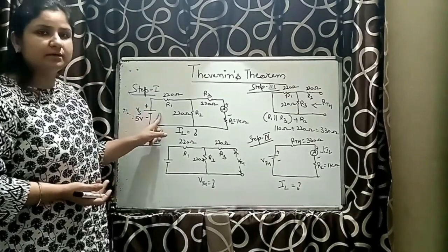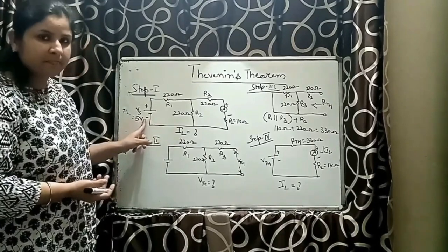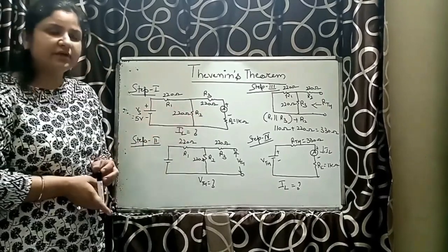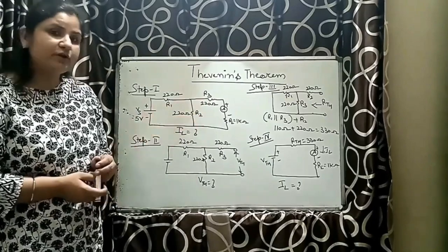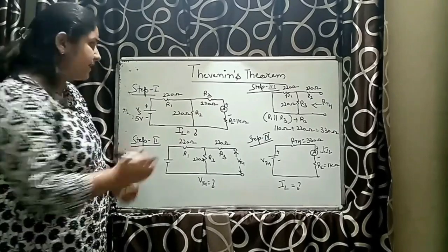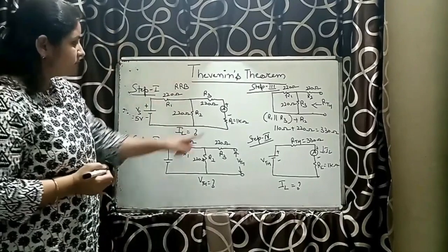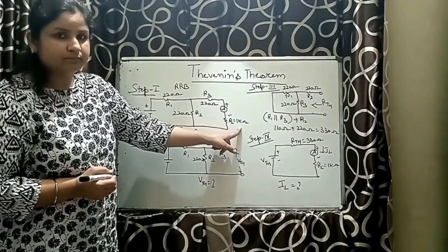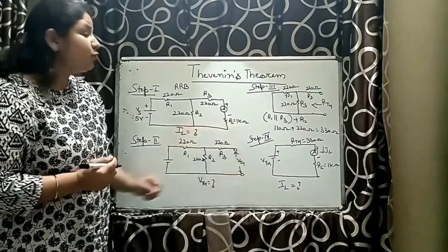First of all, let us consider this circuit diagram. Input voltage Vs set to 5 volt, R1, R2, R3. We have taken 3 resistances which are connected in this arrangement. The value will be 220 ohm, that is, we have red, red and brown. Load resistance 1 kilo ohm, brown, black and red.